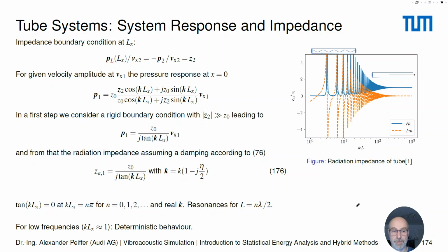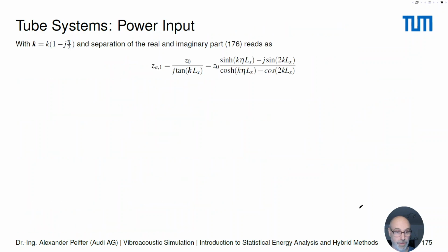So at high frequency, all the resonances and all the reflections are gone, or effectively the second boundary is no longer existing. This is a very important thing in SEA, because when SEA subsystems are coupled, they are always considered as a kind of semi-infinite system. And this is the first occurrence of such hints that this can be done, and this is true. We will later learn what quantity is exactly determining this effect. Good, so that was the heuristic approach.